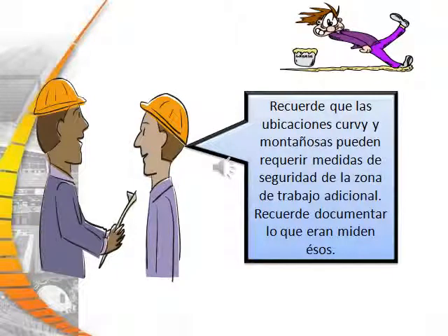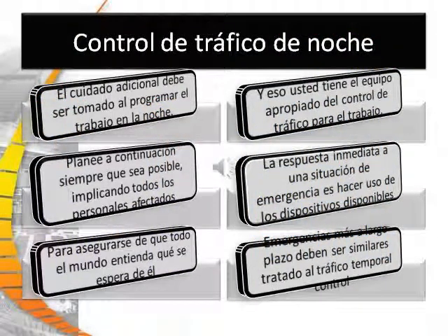Remember that curvy and hilly situations may require extra work zone safety measures. Remember to document what those measures were. Extra care should be taken when scheduling work at night. Plan ahead wherever possible, involving all affected personnel, to ensure that everyone understands what is expected of them, and that you should have proper traffic control equipment for the job.